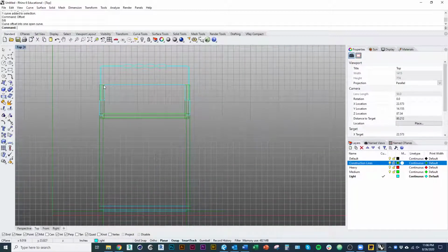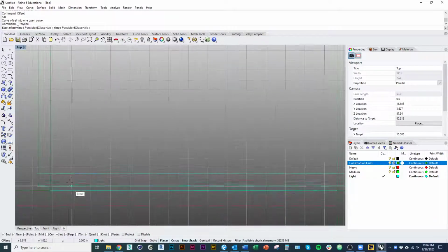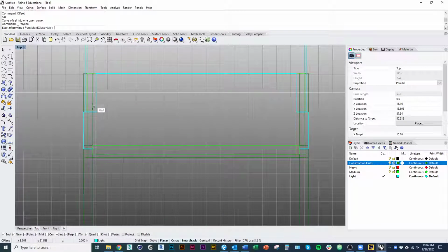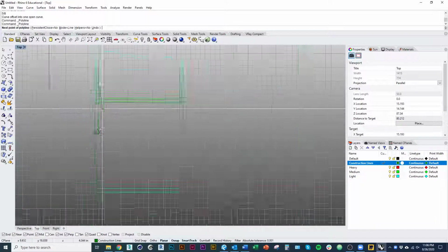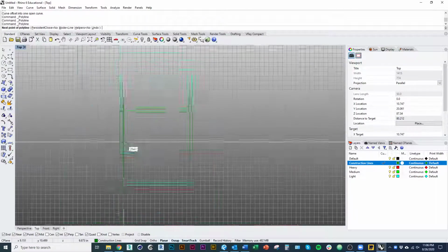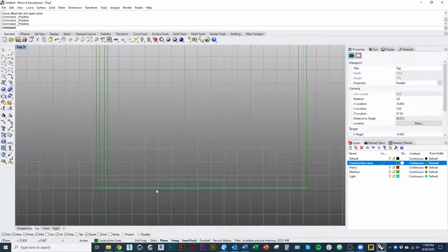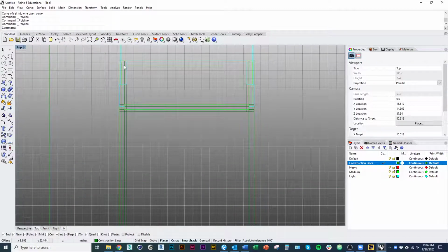And we also know that we would be seeing that plane, for example, and we could start to draw construction lines, start to draw where that would be. So again, rather than redrawing everything from scratch, I'm pulling a lot of dimensions off the drawing that I've already constructed, which will go a little bit faster.